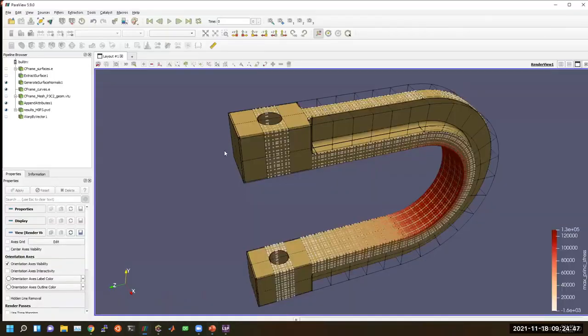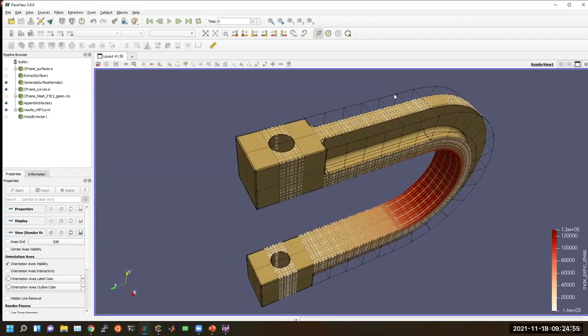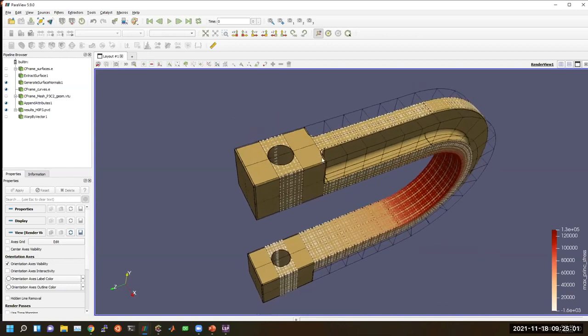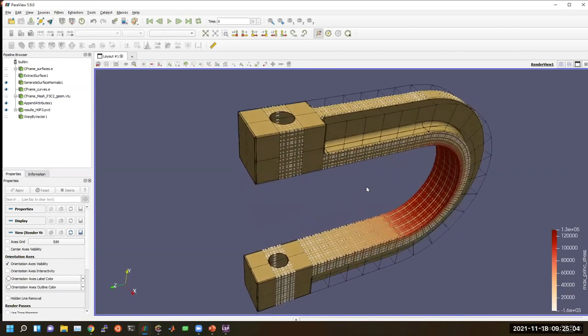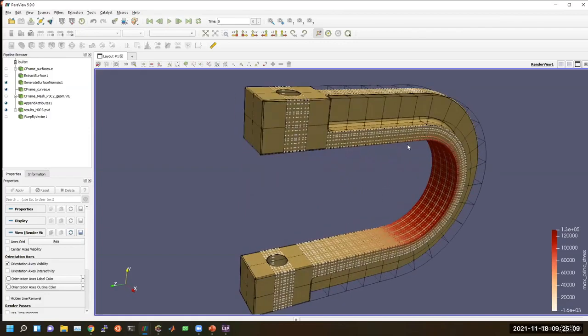But I do have the model that we show in that demonstration shown here. Again, showing in this wireframe outline the U-spline that was used to capture this model geometry, and the results here are shown at the integration points of our model. And we've shown that this representation has very good agreement with traditional finite element approaches, but with many times fewer, orders of magnitude fewer degrees of freedom, in fact. And so this can result in not only a speed up in your modeling or your model prep, but also in your actual run times.